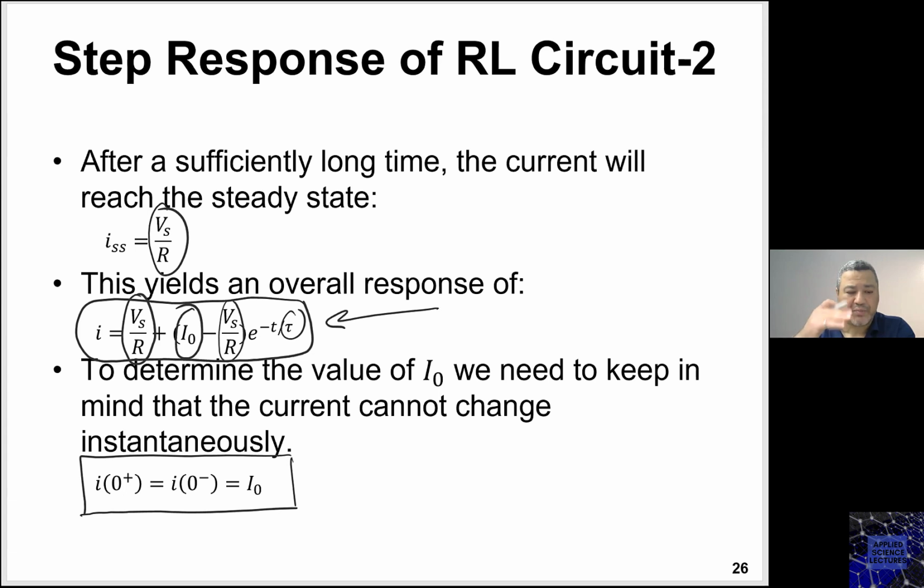It is very systematic, but the most important thing is to understand what those parameters or constants mean. The initial current, the steady state current, and the tau for the inductor, or the initial voltage, the steady state voltage from the second circuit, and the tau from the second circuit for the inductor. When I say second circuit, it is the second position after the switch is moved.